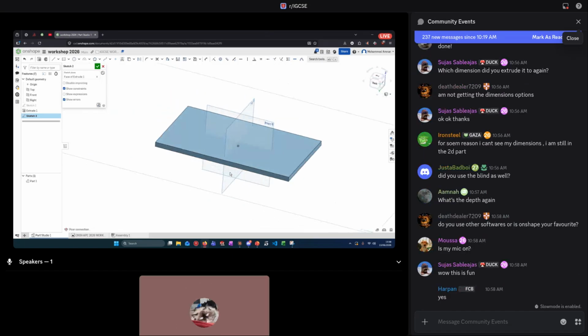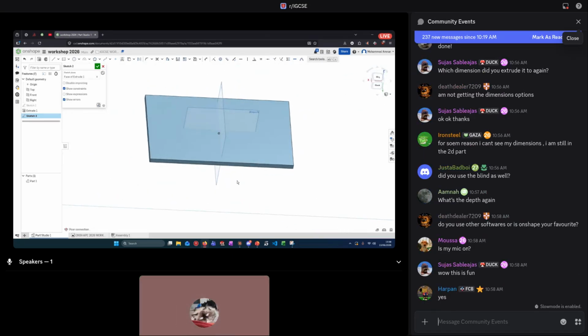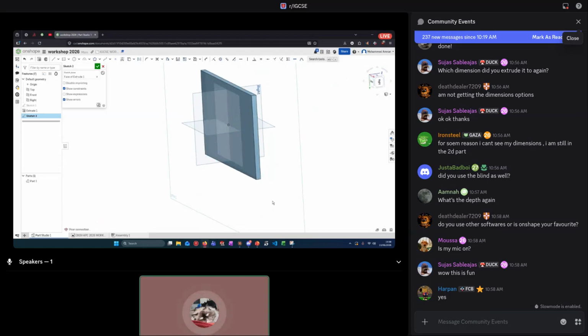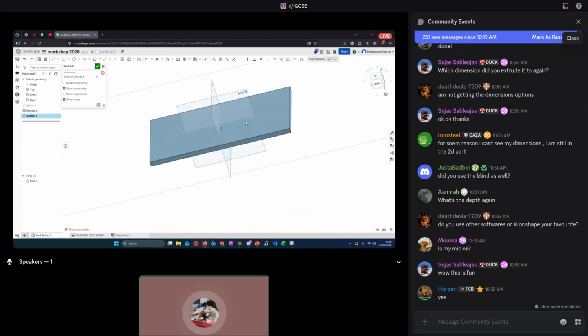Okay. So now right here, we have the new sketch, and the sketch should be on the top of this part. If you made a mistake, don't worry. Just press X, come over here, sketch, and then just click on the thing again. If you've selected anything to deselect, just press Escape.